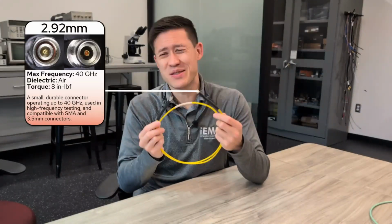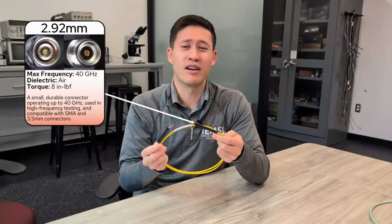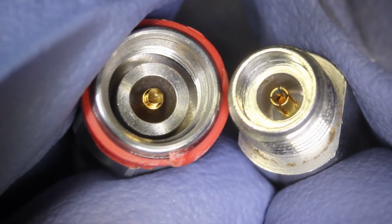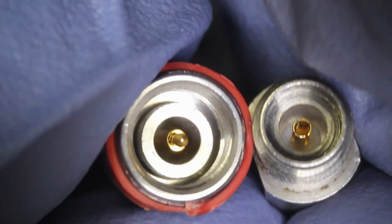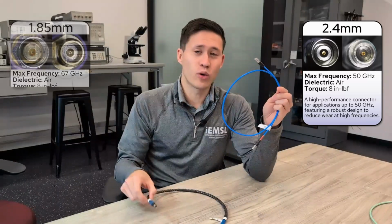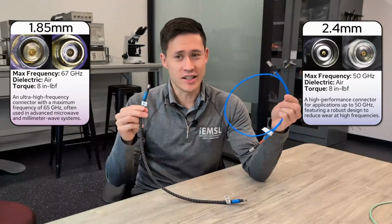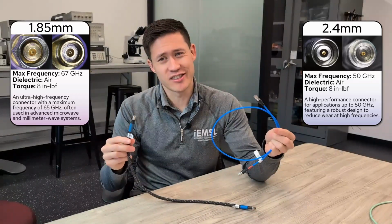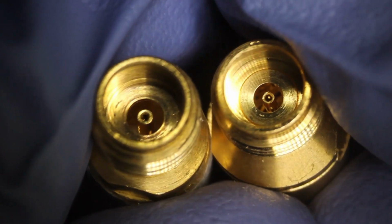The same is true for the 2.92mm connector, which we sometimes just call 2.9mm. The 2.9mm connector goes to an even higher frequency, all the way up to 40 gigahertz. The last 2 connectors that we'll look at are the 2.4mm and the 1.85mm. These connectors can go all the way up to 50 gigahertz and 67 gigahertz. You might notice a trend with these connectors, which is that the conductors inside just keep getting smaller somehow. And that's precisely why they're able to get up to these higher frequencies.